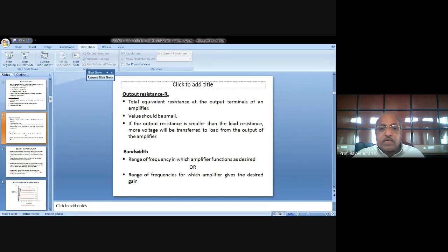And what is the purpose of this resistor? This emitter resistor actually provides the stabilization, the compensation for temperature variations and all those things. And VB is the biasing voltage given by VCC. VCC is common to all. That is the voltage between the positive VCC point and the negative, or earth point.